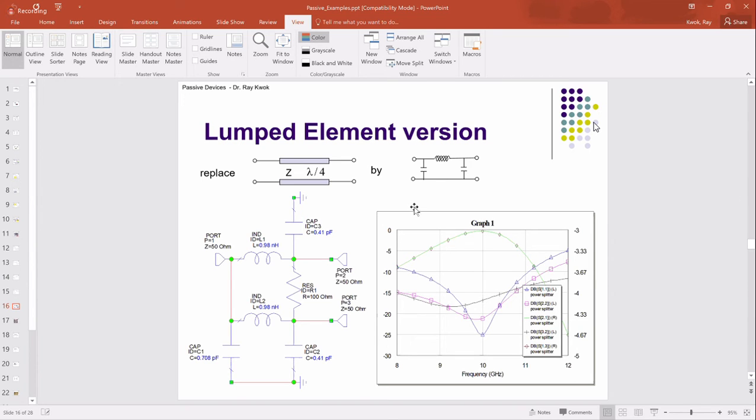Moving on now, that's not the only way to do the Wilkinson. Sometimes people remember a transmission line, you can write it as a shunt cap and a series inductor, right? So you can also write the transmission line as a pi network. Depending on how you put it, you can write it as 2 inductors and 1 capacitor, or 2 capacitors and 1 inductor.